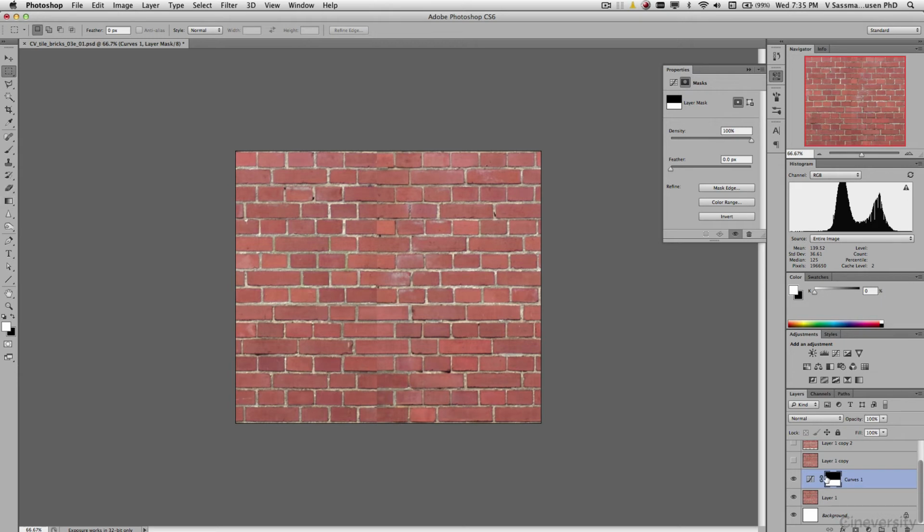And what I need now is, of course, that I have from the bottom area a black gradient that stops pretty much in the middle here. That means I go to my gradient. I have made certain everything here is black and white, and I have now here a gradient that is half transparent. It's white, that's not usable, so I press the X key one time and I get black, and I start here from the bottom. I move this up on purpose a little bit in the wrong direction, press the Shift key, and it switches over to the other direction.